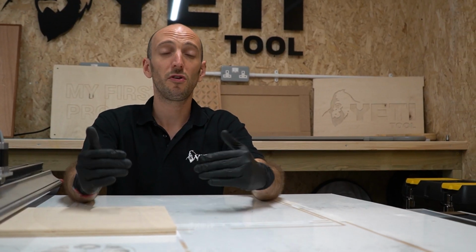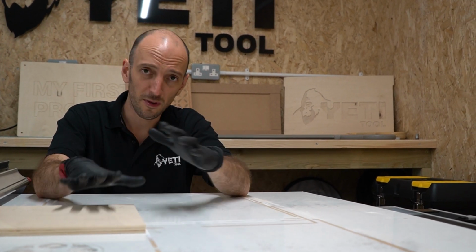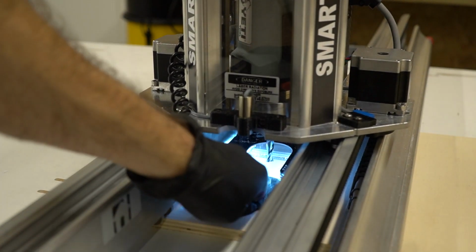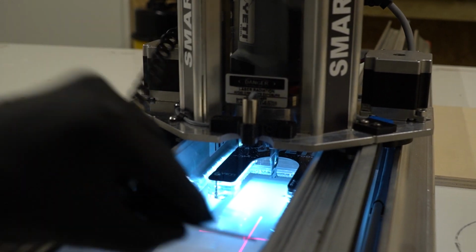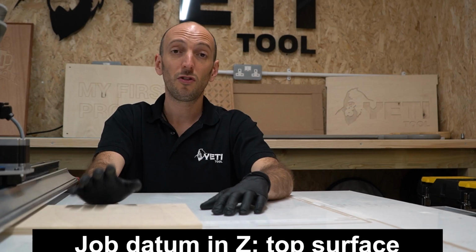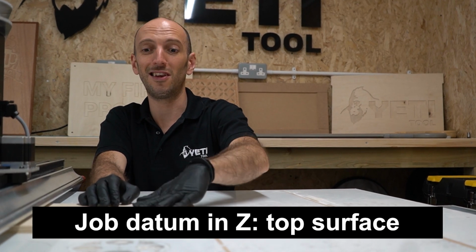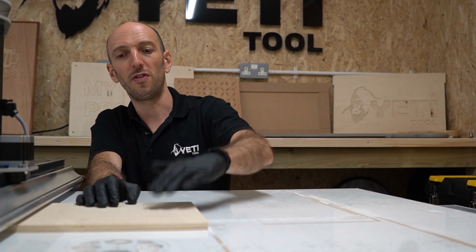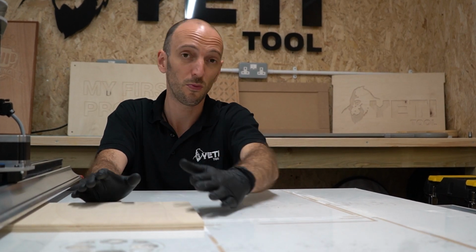Now let's look at the options in the Z-axis. So you've got two options when setting the datum in the Z-axis for your job file datum, either the top of the stock or the bottom of the stock. The top surface is the most common, and that's because it's easy to access. I can easily get a probe plate to touch this. Also, it's fantastic if you're engraving, because you're making sure that the depth of that engraved cut is relative to the top surface of the material, which is what you care about.